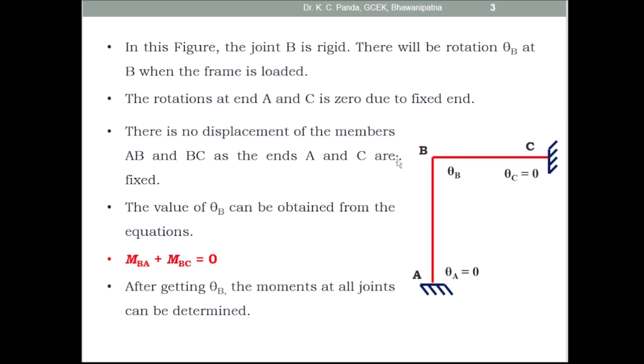Then after knowing theta B, the rotational displacement at B, you can find out the moments at all joints by putting this rotational displacement in the slope deflection equations.